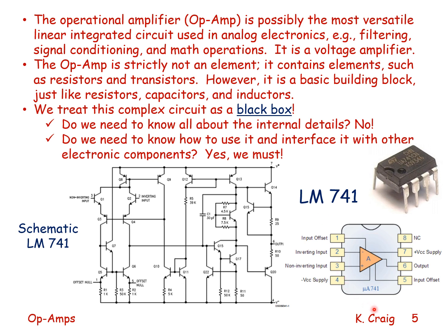Here is a diagram showing the pinouts of the 741 op amp. Pins 1, 5, and 8 are usually not connected. Pin 3 is the plus or non-inverting input. Pin 2 is the minus or inverting input. Pin 6 is the output. Pin 4 is the negative voltage supply. Pin 7 is the plus voltage supply.